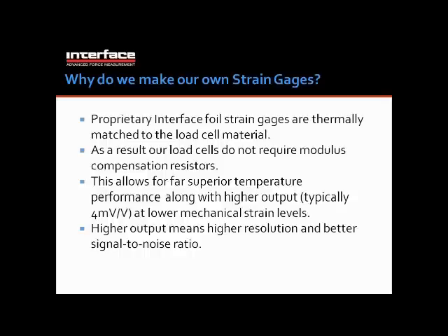Many of our load cells are 4 millivolt per volt, and that can be achieved at lower actual mechanical strain levels of the flexure itself. So higher output means higher resolution, better signal to noise ratio, and more confidence in your measurement.